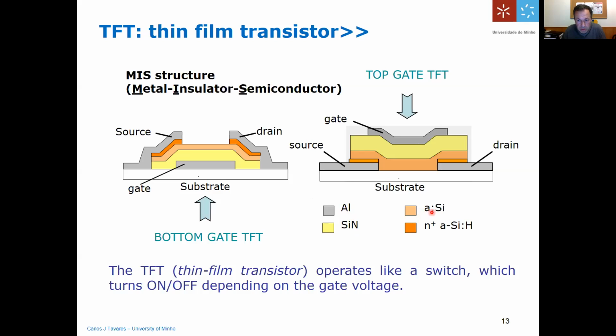then amorphous silicon, and on top hydrogenated amorphous silicon, which is p-doped, which has a positive polarity, or it's doped with holes. It's not n-doped. And the same thing applies for top gate TFT.